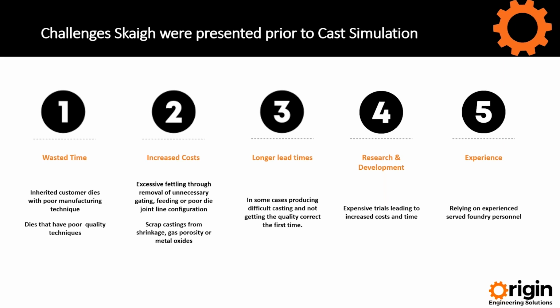right at day one. And we always want to do research and development, but doing trials in gravity die is not cheap. You're having to send the die into the tool room, do a trial, cut metal out, not helping the die properties because now you've weakened the die. So it's so hard to do development in a gravity die casting, and we're relying on people's experience on the shop floor, myself and other colleagues.